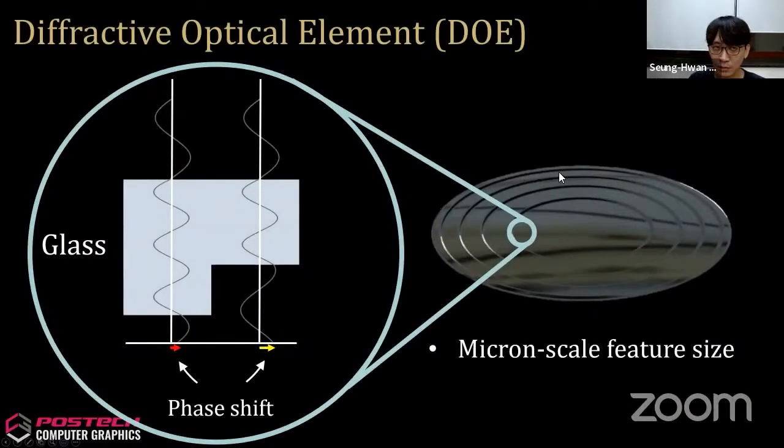Here, one thing to note is that the illumination pattern made by this active stereo system is determined by an optical element called a diffractive optical element, DOE. This DOE is a simple optical element made of really small slabs of glass with different thicknesses.